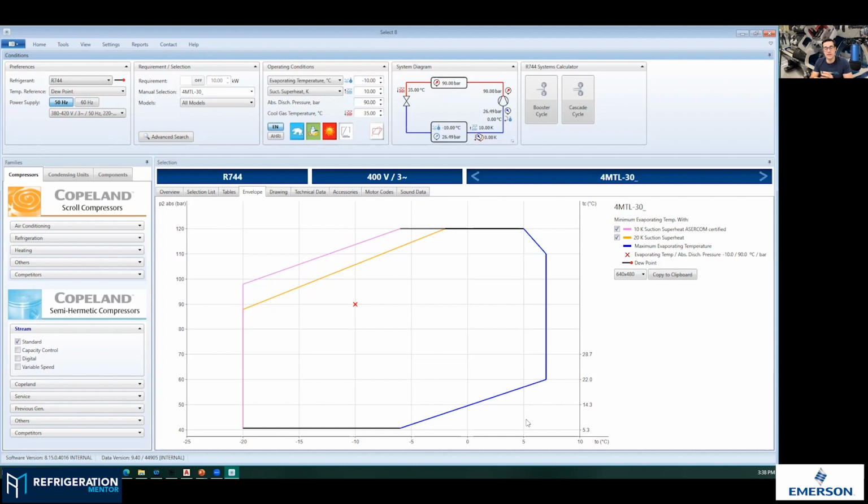That is the most important thing, because a lot of the times when this is happening as a technician, we're not there in the field. It's happening when you're at home or at another job site. Then you get there and the compressor is either not running or it could be failed. You really need to understand this, but if it's not running, you can't really put the gauges on. But if you see and notice this, and this will happen especially here in Canada when it's really cold, like today it's not super cold where I'm at, but I know in northern Canada it's like -30, -40. If you don't have the right components in play, say maybe head pressure controls that keep the head pressure up in low ambients, you may run into this.